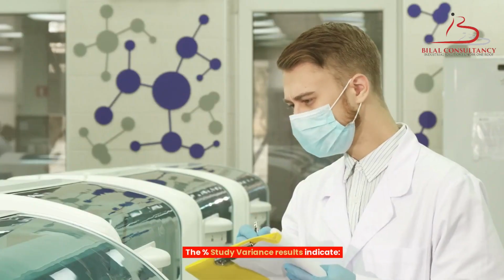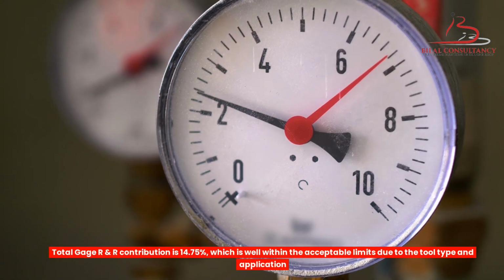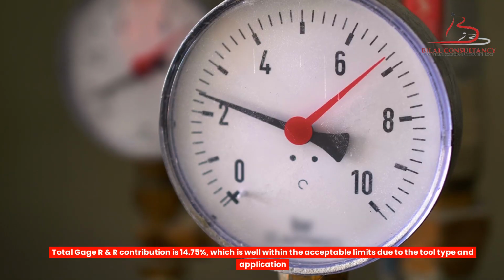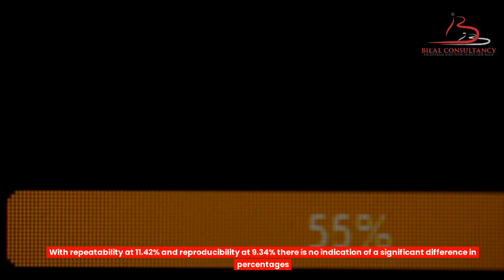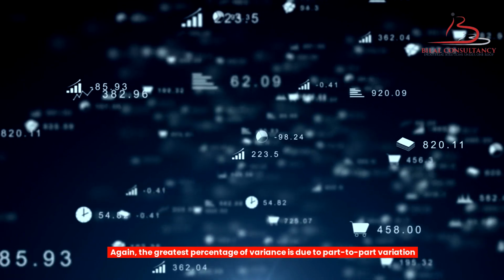The percent study variance results indicate total GageRnR contribution is 14.75%, which is well within the acceptable limits due to the tool type and application. With repeatability at 11.42% and reproducibility at 9.34%, there is no indication of a significant difference in percentages. Again, the greatest percentage of variance is due to part-to-part variation.